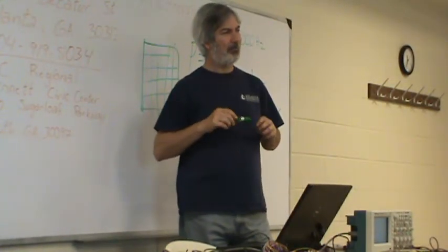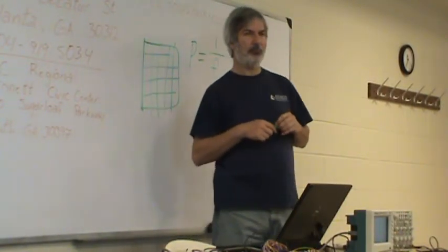I think a more general answer is it's what technology you're working on. For example, if you're working on I2C, you know it's going to be around I2C's frequency. You can just look at what I2C's frequency is, and so you know to expect that frequency. So go ahead and set my equipment to that range. So that would go back to the spec sheets.